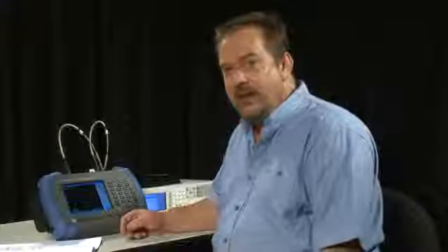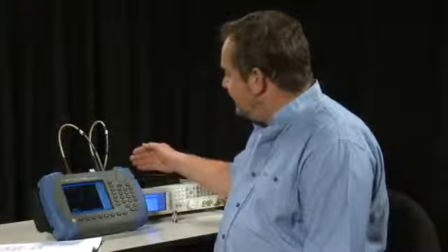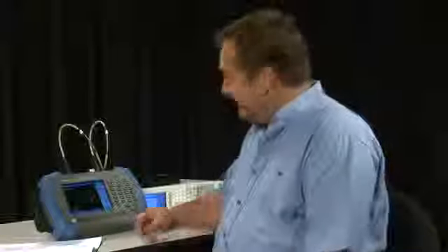Now, as you know, when making network analysis measurements, even simple ones such as this for the insertion loss of this filter, we are actually making a relative measurement, not an absolute measurement. In other words, we're comparing the frequency response of this filter with a known standard device. In this instance, I'm going to use this N-type through, and I'm going to assume that this is perfect